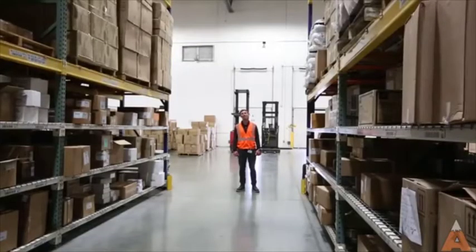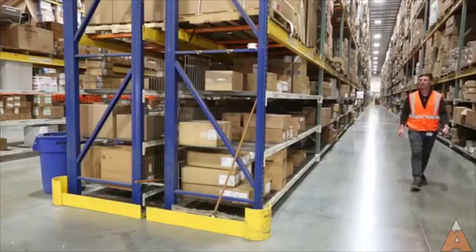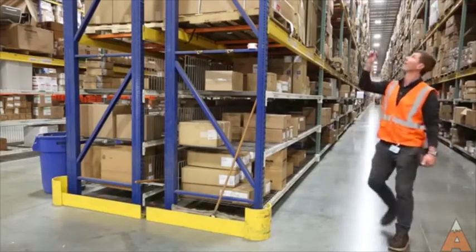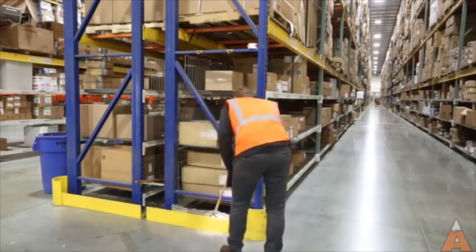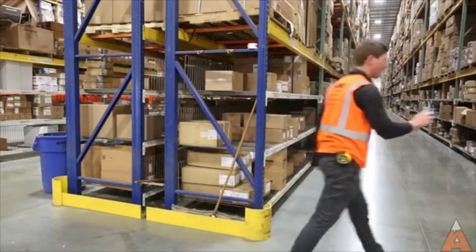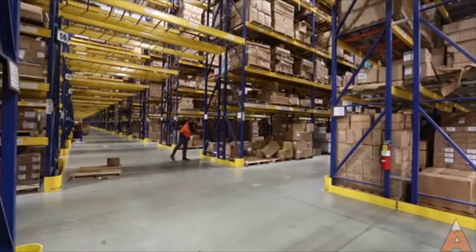When entering the row, scan the aisle to identify any obvious imperfections. In many rows, the beams will be at the same height for extended stretches, providing a good view to spot damaged or sagging beams. Start your way down the aisle, taking time to inspect each individual upright and beam. Use your flashlight to inspect both up and down the upright. The light makes it easier to see imperfections in the steel.